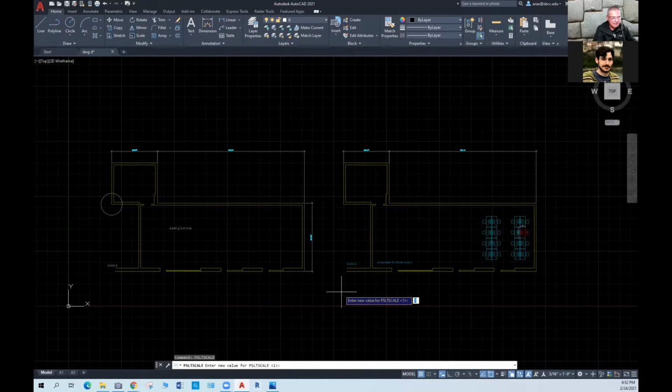And that final number is the one that defines the size of the line types in your print drawing. So as you can see, it becomes confusing. So the best practice then is to set it to 0. So that whatever you see on the model space is what you get. It does not get multiplied by the scale of the viewport.